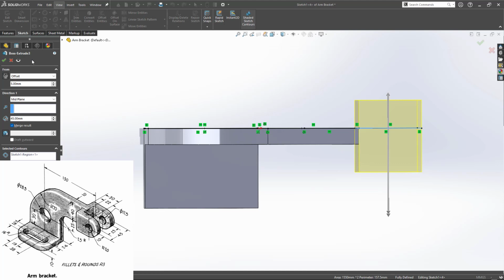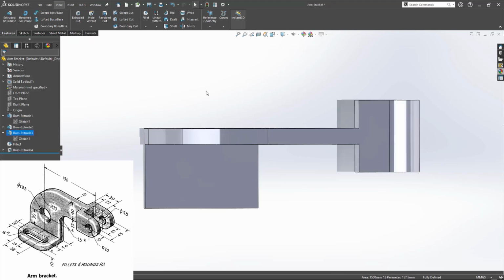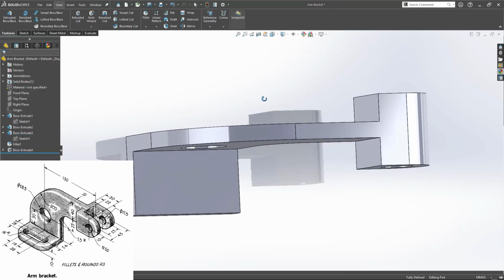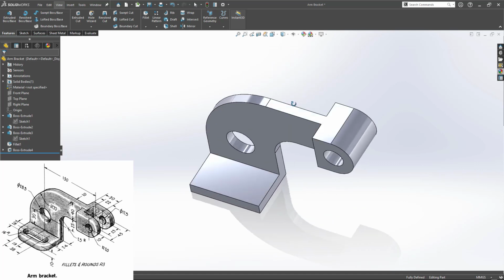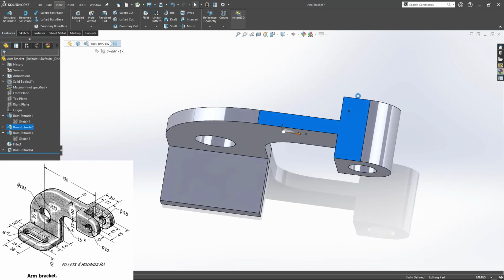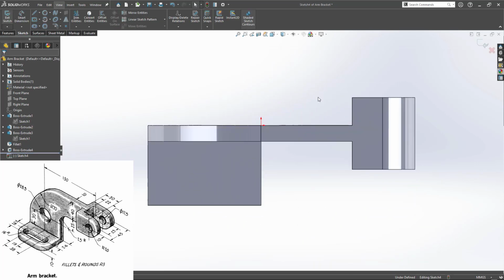If you take it 5 inside offset, it will start from the center. I feel so. This should be perfect. Let us measure this. 17.5. This is also 17.5. Yeah, now it is fine. Take the top plane, and here the cutout is 25.